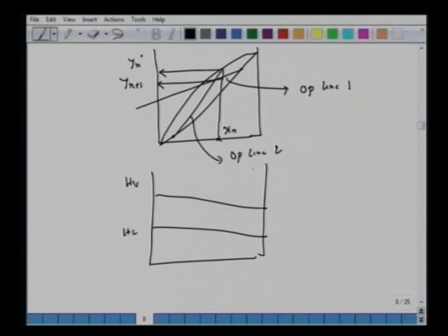So again we locate a difference point, delta, so that if we have yn plus 1 here and connect this, it will give us xn. Xn, on the other hand, is in equilibrium with yn. So yn versus xn is given by the tie line, and yn plus 1 versus xn is given by this operating line. So what is the operating line? Nothing but this mass balance or species balance. Alright, so these are all steady state processes.